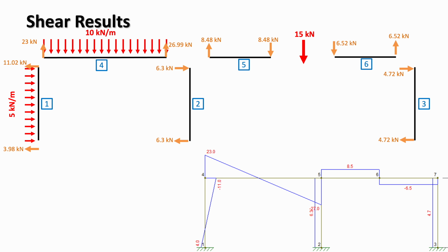This confirms that the shear forces have been computed correctly, and that our sign convention and transformations were applied properly, and that the fixed end contributions from the distributed loads were included in the right way. It also reinforces that the code is capturing shear behavior of the indeterminate frame as expected. However, we must note that in the stiffness method, we only get values at the ends of the nodes, so we do not see, without drawing the diagrams, what happens in the middle of an element.